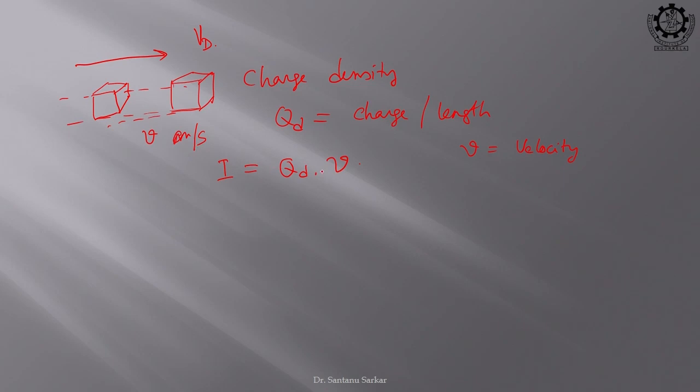So, if we multiply our QD, we will get the current. Now, we all know that when the channel is inverted above VTH, the effective gate to source voltage should be above the overdrive voltage, VGS minus VTH. There is no doubt about it, because only after it crosses VTH is the channel inverted. So, this phenomenon will be happening.